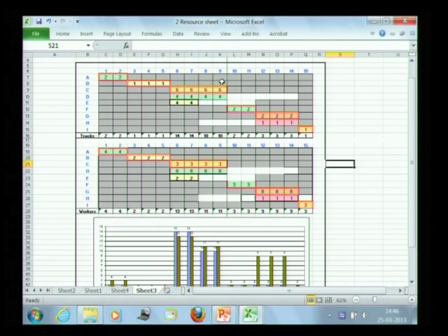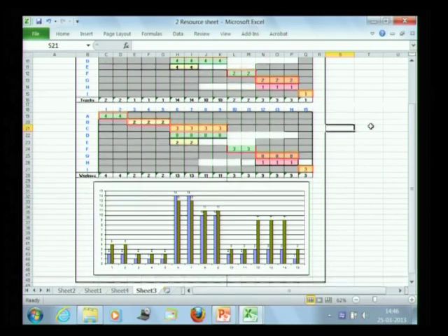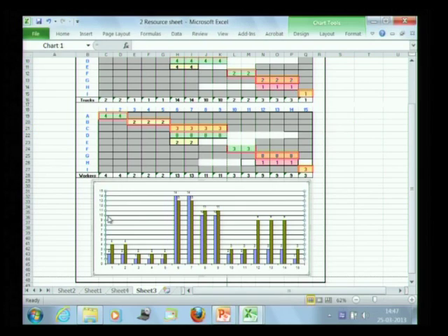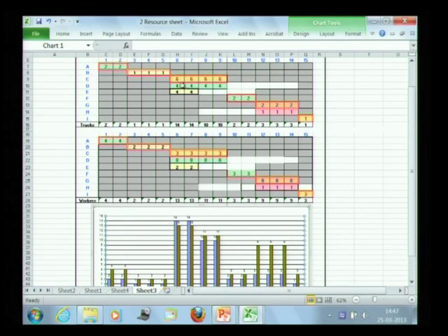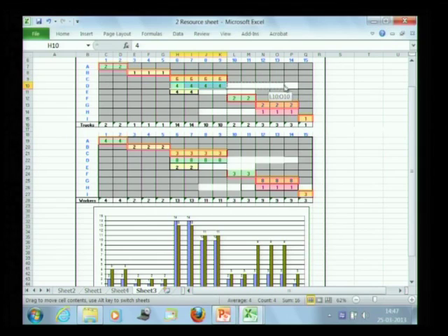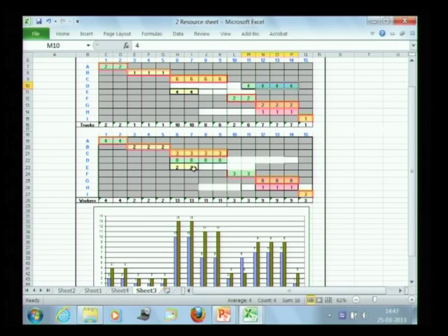So this is for each of the resources, and you can see that we had 14 trucks and 13 workers. My truck is over allocated because I am only allowed 10. Now my first reaction, at least as a simple approach, might be to go to the late start.